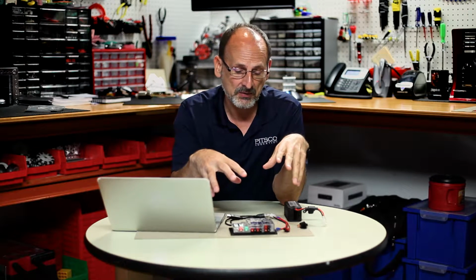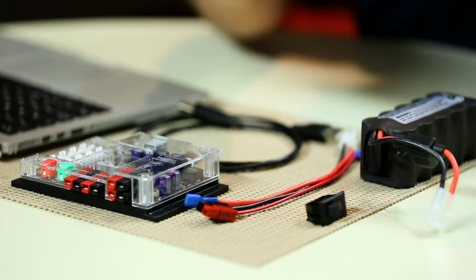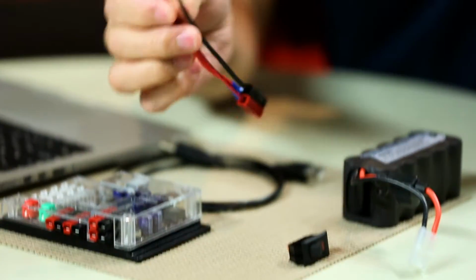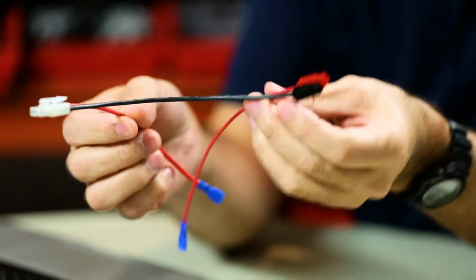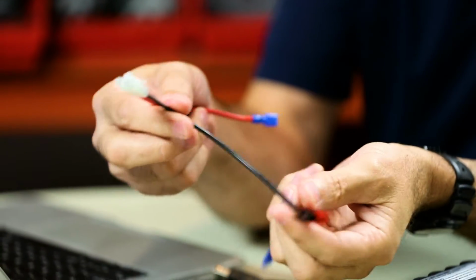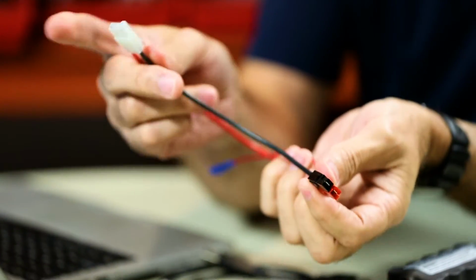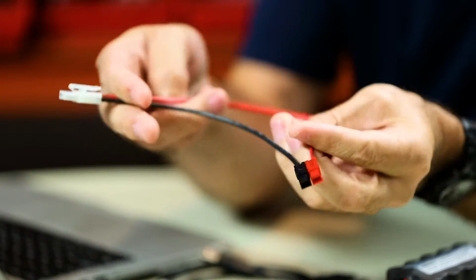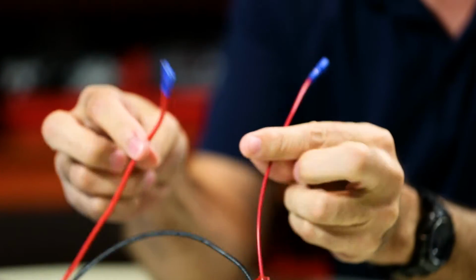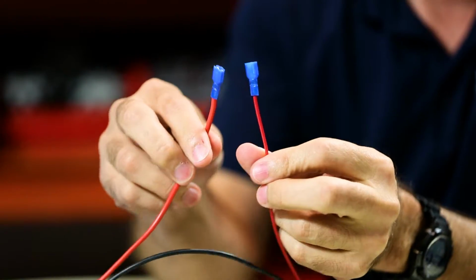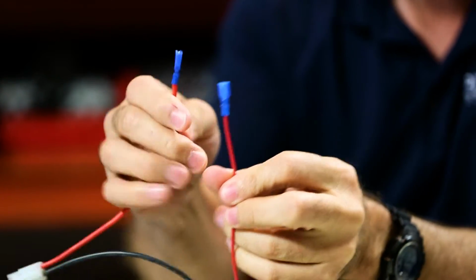Now, we're actually pretty close to ready to download this already. That's all it really takes. But before we do, we need to make our physical connections. So I'm going to start with those physical connections by hooking up my switch harness. So I'm going to take my cable. There are two connector ends, one for the battery, one for the PRIZM, and two open ends on the red side of the wires that are going to attach to our switch.